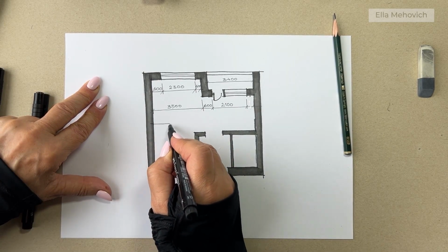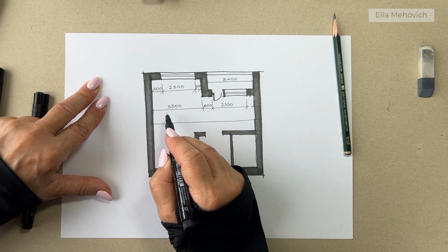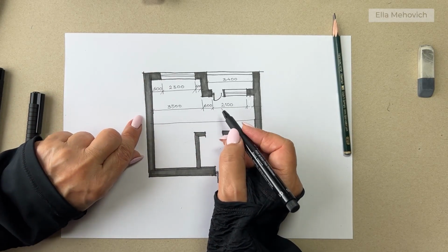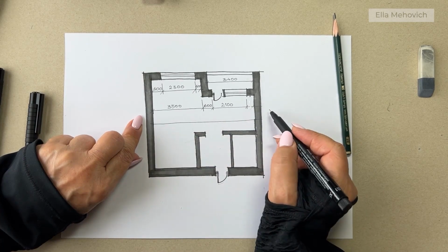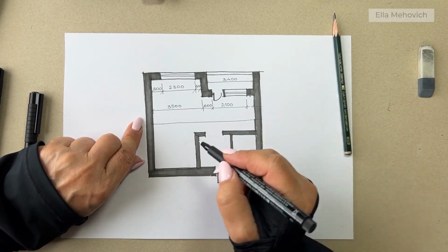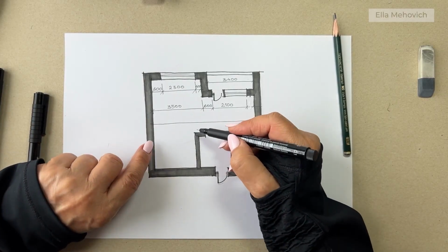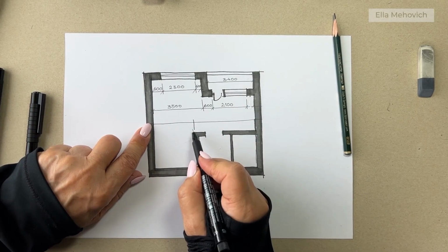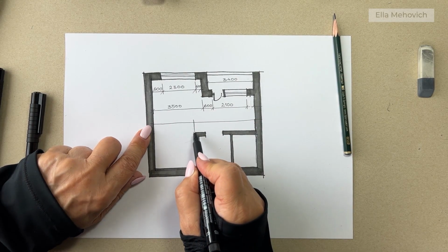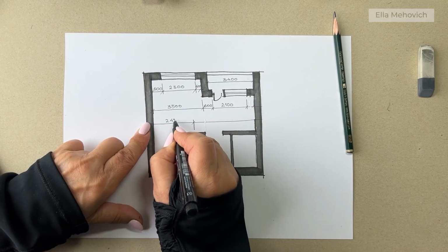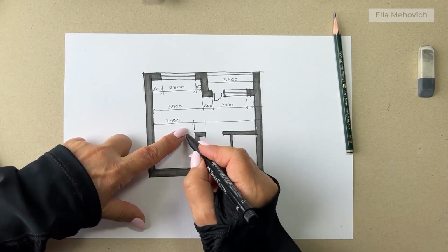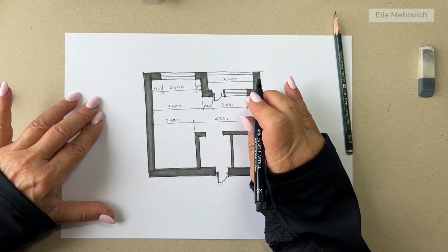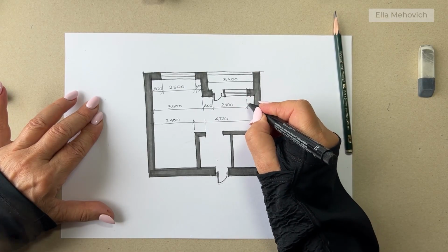Now let's also add the overall dimension. Look, when we put a lot of small dimensions, when we measure the details, then we can also add dimensions that combine the whole chain. And look, for example, if I want to now set the dimension of this niche, I draw the line toward that corner from which I will take the measurement. And don't forget to add these diagonal ticks as well.